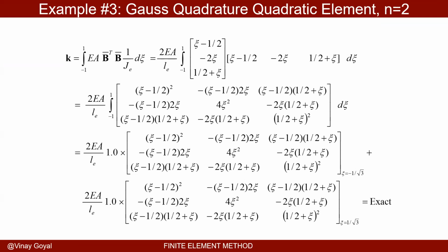So I have a way of converting the problem into a standard element. Shape functions are the same. The derivatives are the same. And it's incredible: the only information that contains the geometry is the Jacobian. That's a mathematical miracle because I'm now able to systematically solve governing equations with different element sizes, and not have to rederive the shape functions for every single element, not have to figure out how to do the integral for limits that change from element to element. I can just look at the standard element and solve it there and then assemble it for everybody else. Okay, so that's exciting. Thank you for listening.